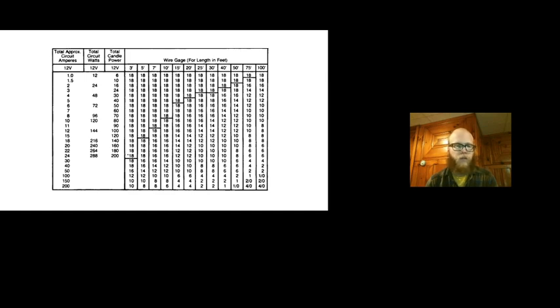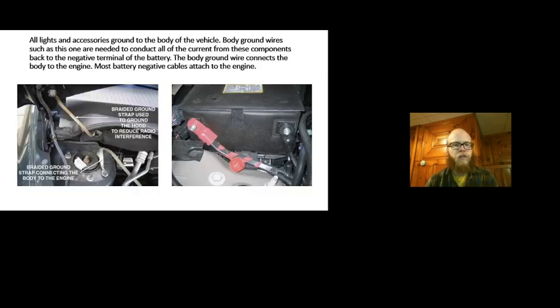So there's no resistor built into it that's creating resistance. It is just the coil of wire that is adding up to the resistance of that circuit, dropping the voltage as the current flows through it and creating that magnetic field that makes the switch close.